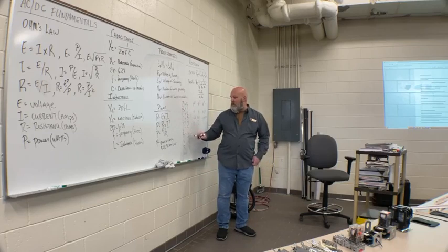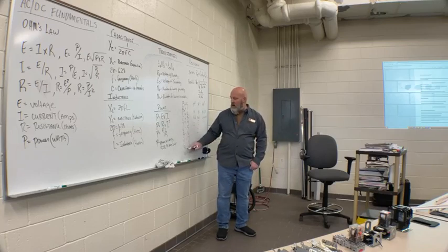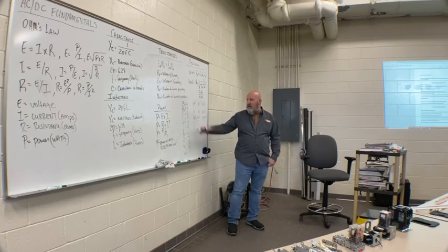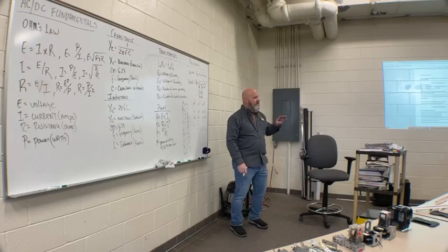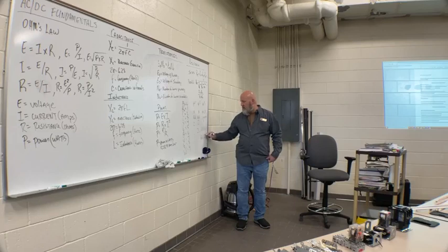Red, orange, yellow, green. You have to remember this is blue. The other color with a B is blue, violet, gray, and white. So you look at the color codes and you assign it the values. And then here's the problem that the students have. If it's gold, it's plus or minus 5%. If it's silver, it's plus or minus 10%.